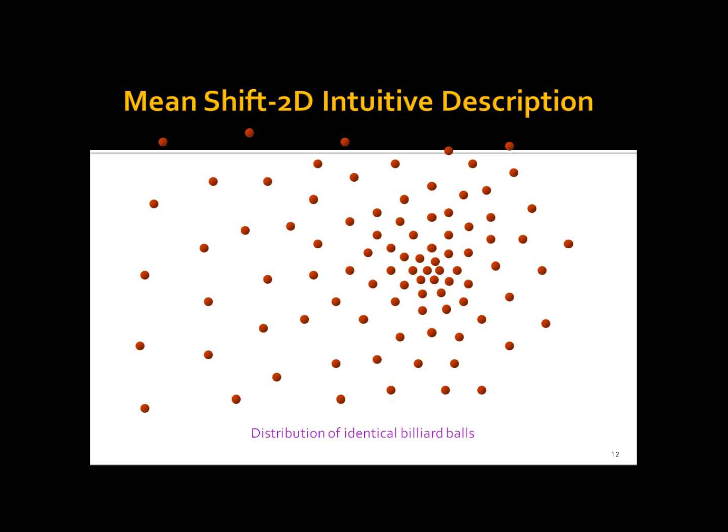The range image is segmented using the mean-shift segmentation technique. It consists of two steps: filtering, known as discontinuity preserving smoothing, followed by clustering. Centroids of the clusters are then delivered to the tracker as a measurement set. We can see in this illustration an intuitive explanation. Given a region of interest, which is defined by the bandwidth, we search for modes, which are the local maxima points, by calculating the center of mass of the region.